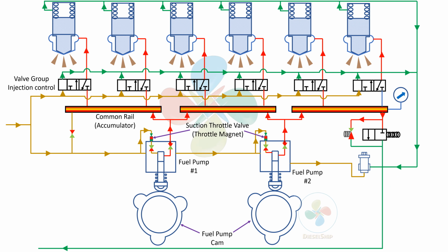Why? Because a mechanical engine, please listen to what I'm going to tell you, how and why should we go to this common rail engine, which is so complicated and does require the help of electrical engineers. Days are gone when ships required more mechanical engineers and fewer electrical engineers. Things are changing slowly. The engines these days need as many mechanical and electrical engineers, right? Why do we need electronic engines? Electronic injection is so flexible, right? To handle the emission requirements, the engine should have a certain quality and flexibility of injection.